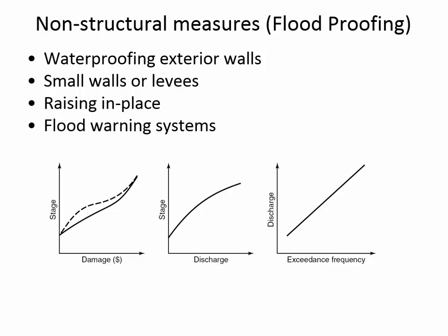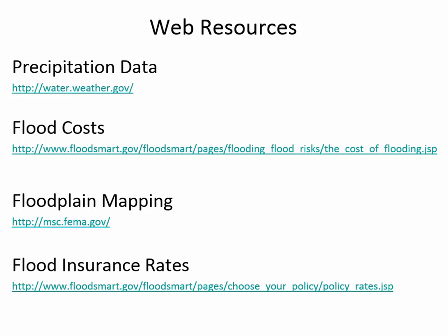And so choosing building materials that are suitable for a flood-prone area, just doing this in isolation doesn't change the hydraulics or the hydrology at all, but what it changes is if the water level gets to a certain depth, how much damage there's going to be. So for a certain depth, instead of a lot of damage, you're having less damage. If you use cinder blocks instead of drywall, when the water level comes up through your house, you're not having to replace all that drywall, so there's less damage for a certain depth. You're trying to, in other words, ruggedize the house so that there isn't quite the same cost that there otherwise would be. I'm going to save this slide for next time.